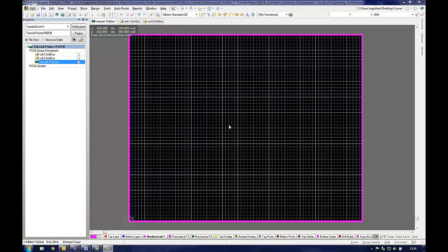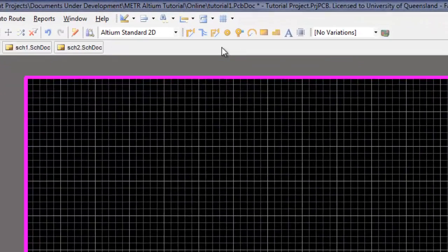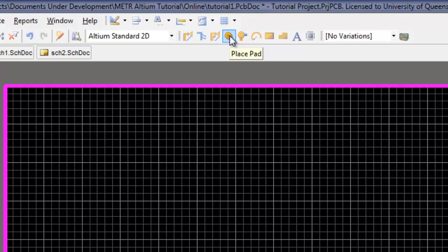The coordinate system can also be used to accurately place mounting holes and any other physical structures on the PCB. The user should place mounting holes onto the PCB at the start of the design and lock them into place so that any subsequent design work takes account of the mounting holes and other structures. There is nothing worse than completing a complicated PCB and then having to rework it because mounting holes have been forgotten about. To place a hole, select Place Pad from the toolbar.